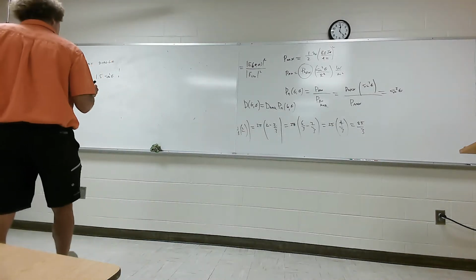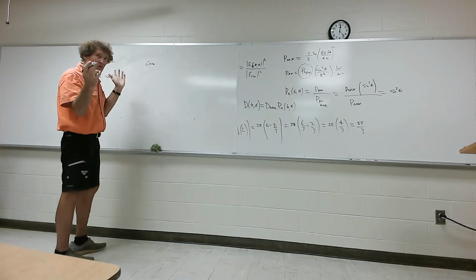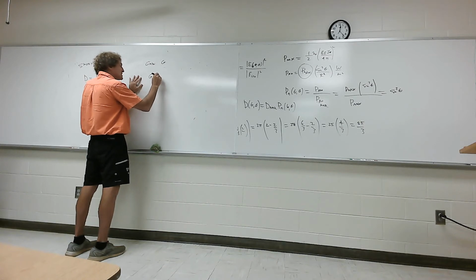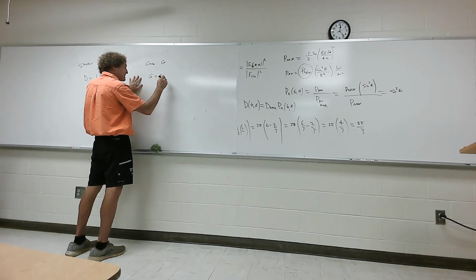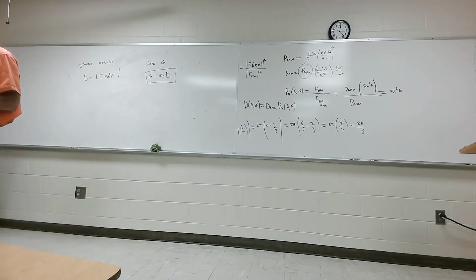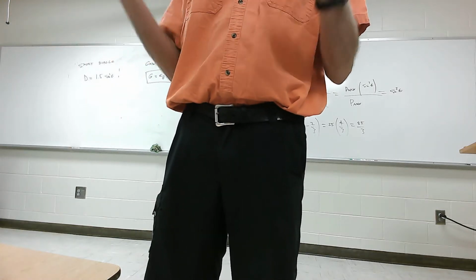So what they do is introduce the term gain. Now gain takes into account all the losses. And gain, symbol G, is really the efficiency of the antenna. I'll call it EF, in this book he has it as EP. And then it's times the directivity. So gain can be no greater than the directivity, but it can be less, not a lot less. Typically, the efficiency of an antenna is 95% or better. So you'd note that E, what I have there, EF, which is the efficiency, it would be 0.95 maybe to 0.99. Y'all follow me? Anything less than that is horrible.